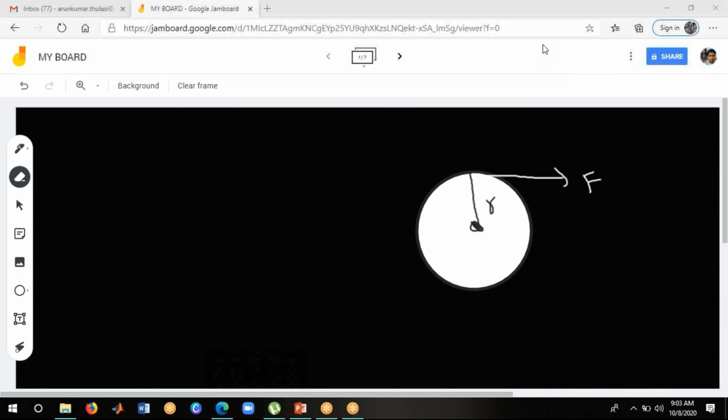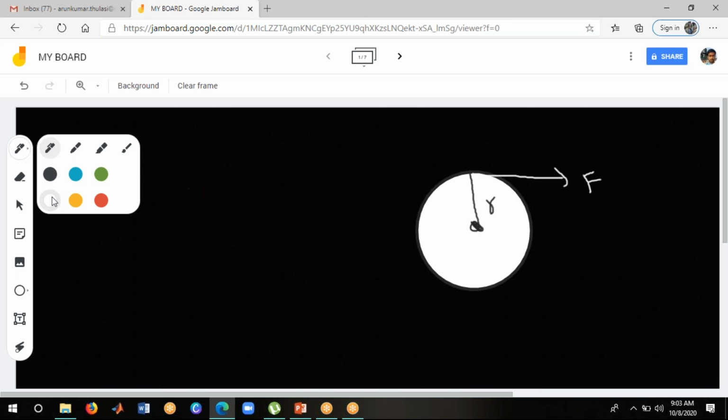Right. See, already we know that for a DC motor, we are always talking about output energy, that is mechanical energy, right? So the parameter which is related to the mechanical energy is torque. Now, let me see the steps we follow to derive the torque equation of a DC motor. First of all, we need to find the torque equation for a given pulley. Why? Because the rotor moves in a circular path, right? That is like a pulley.